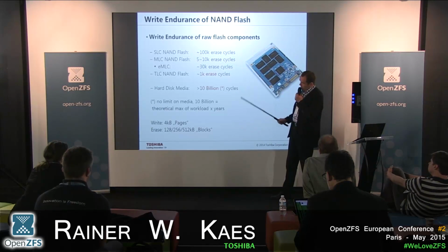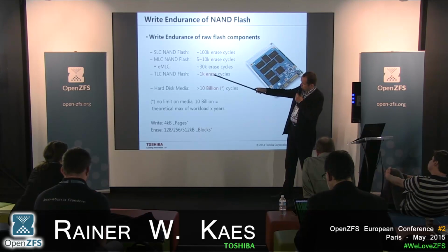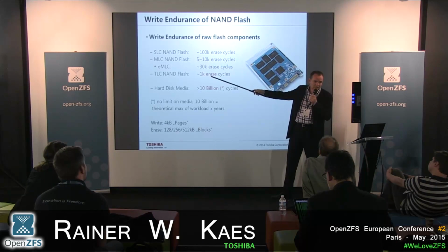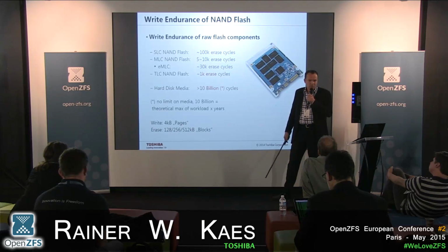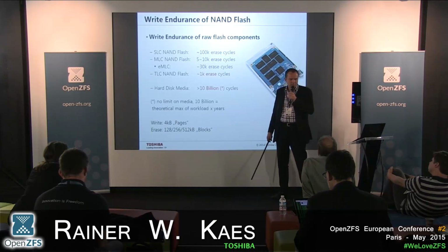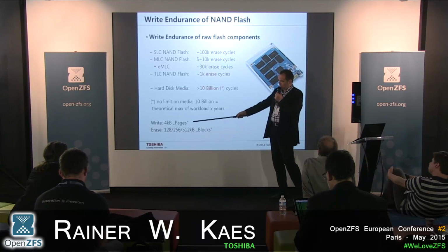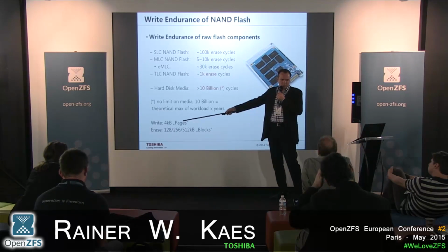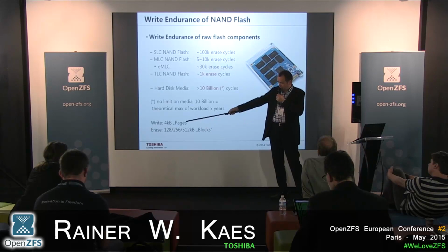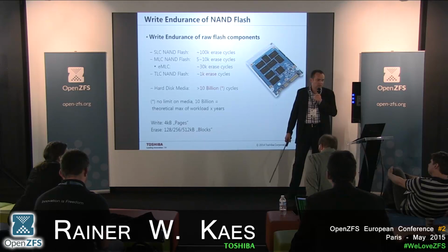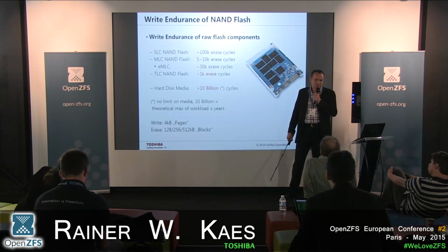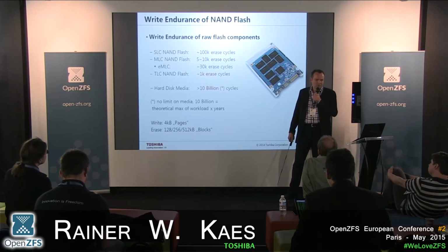So this is why these erase cycles of the single cell do not really map to the full capacity of the SSD, because we have what we call write amplification. So if we write many small pages which are scattered in the larger blocks, we may have to erase a lot of unnecessary data, which consumes the valuable resource.